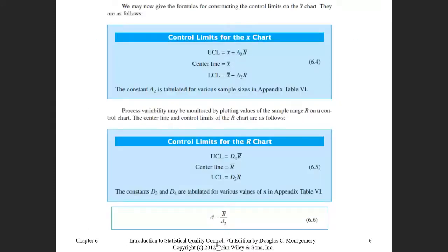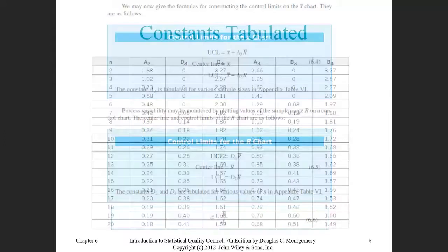This is how we calculate the control limits as well as the center line for each control chart. So basically, at the end, when you implement an X bar R control chart, you come out with two plots, one for the X bar and one for the range.